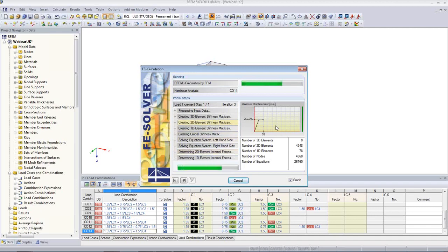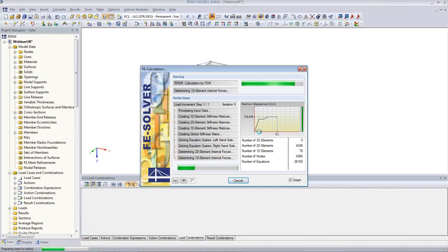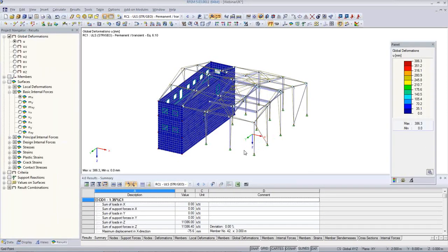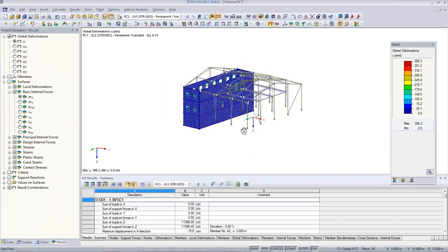These diagrams here show you the maximum displacement, and you see if everything is converging, it stays the same. If it's not converging, it may run away, and it's an indication if there's something going wrong or not. So it's important information about the iteration process and how things are handled inside the solver. I'm running this analysis on a standard laptop. We don't need any major machine, 64-bit Windows, and I actually have only 6 GB of RAM here, so it's nothing spectacular.